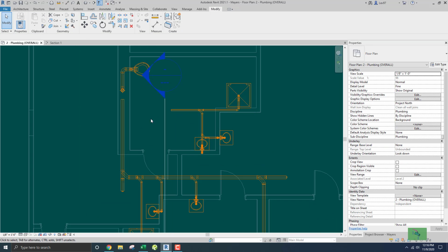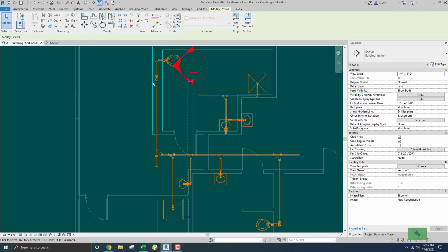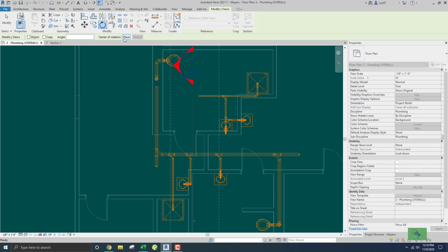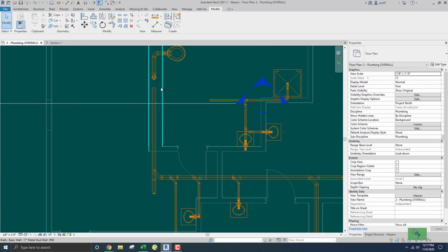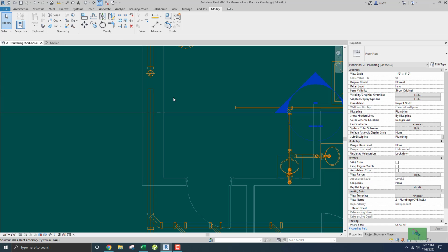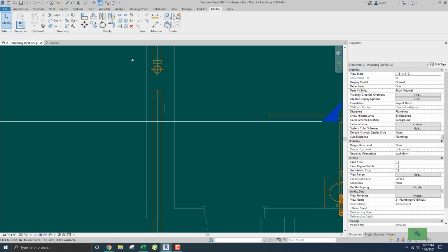So now it looks like I'm going to have to adjust my 2-inch that's coming from my two lavatories and my shower, right? So I'm going to place this view rotated clockwise 90 degrees and get it right there. I'm going to bring this guy a little closer, draw another detail line, maybe right there, and extend that 2-inch to about right there.